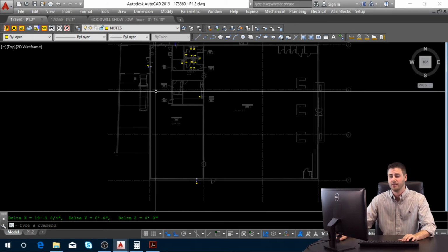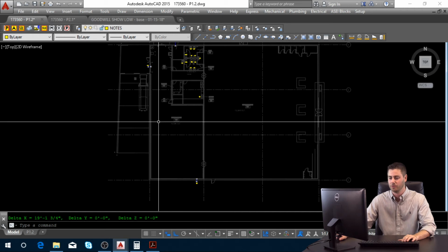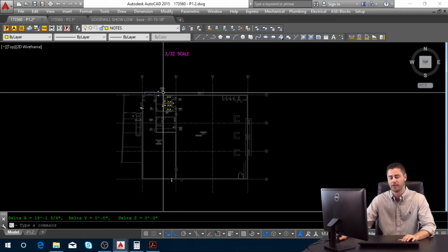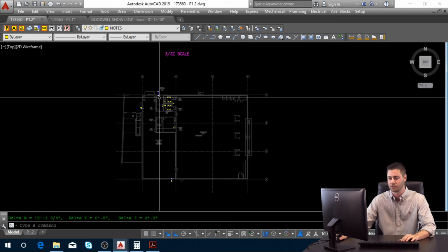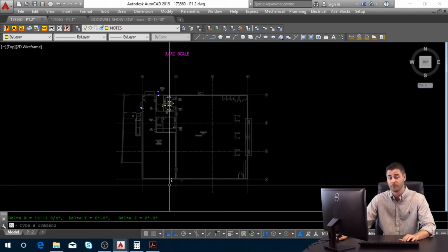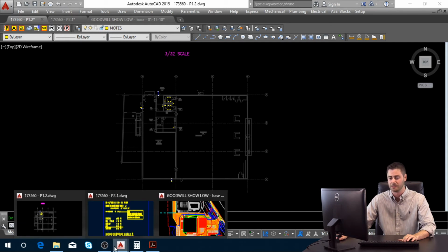It's always important to make sure you include your vertical distance. That's the distance from underground all the way up into the roof structure, because water piping is always run tight to the roof structure, and then back down the wall. So you need to add up that total distance.